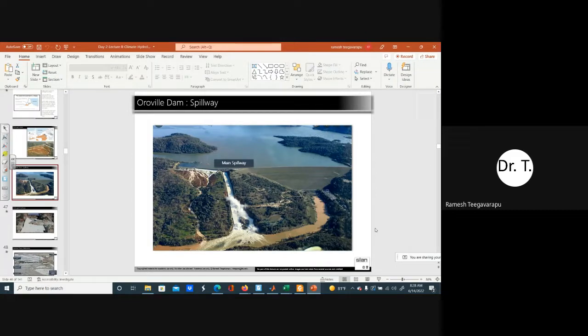Once the water comes to your reservoir and fills it up, we can't do anything. And that's what happened with Oroville. The people were thinking that maybe they would not have a lot of rain because we were not seeing rain in the last days. They had not monitored the soil moisture conditions upstream of that particular reservoir. So they were not anticipating the amount of rainfall which this event caused. They were confident that the spillway could be used to transfer the water from upstream to downstream, but unfortunately the spillway also failed.